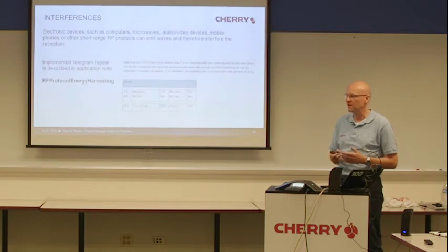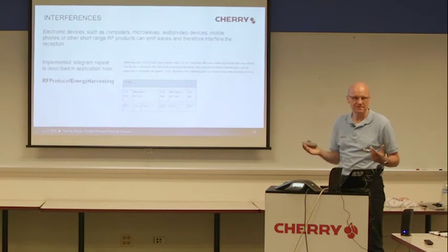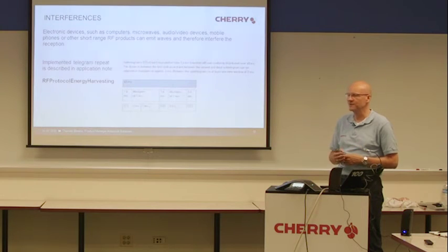It's not a 100% assurance against interferences, but it decreases the risk of interference and of a collision of the telegrams. You cannot give a 100% assurance that every telegram reaches the receiver, because if you install 100 switches in one surrounding or in one application, then the risk of a collision increases more and more.